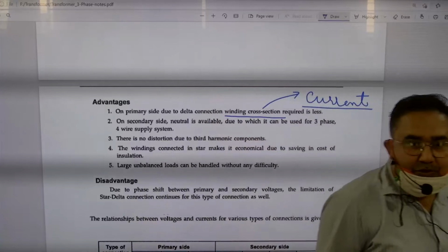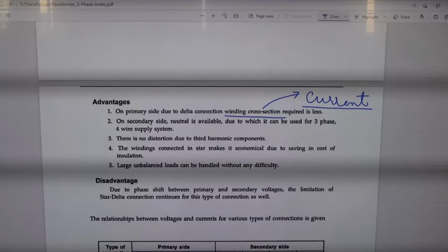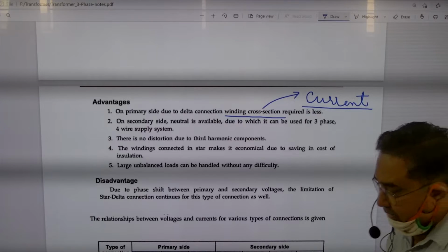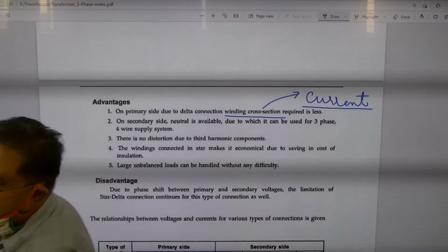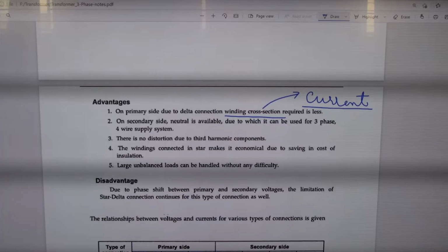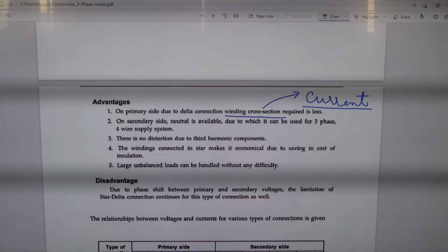As I have already told you, I gave you some practical aspects of wires one day in the class, that wires are selected according to the current capacity. For example, for your fan and tube lights, which wire is comfortable, of what cross section? 1.5 mm square.